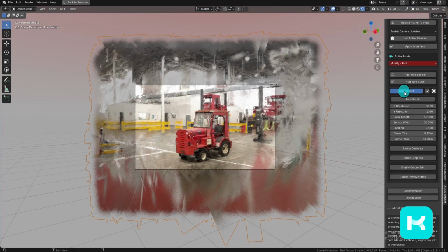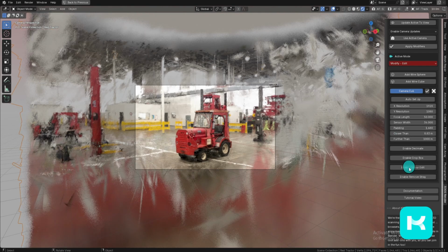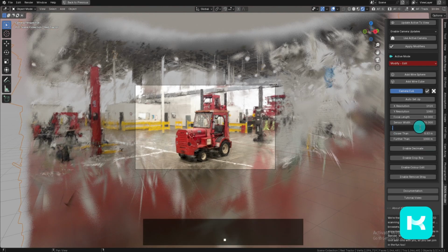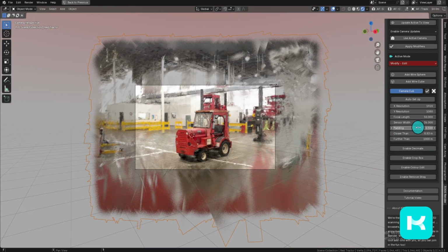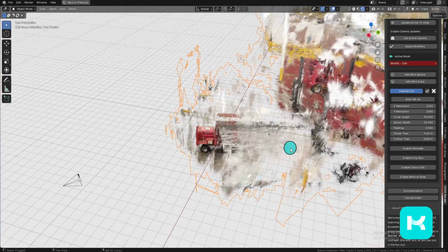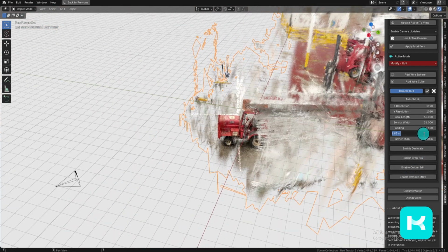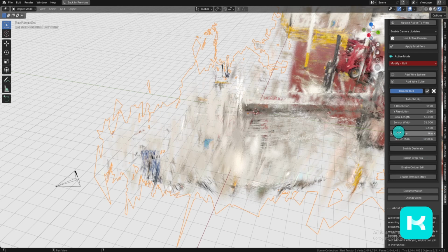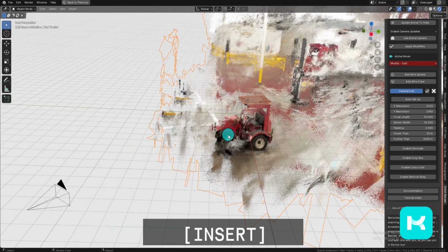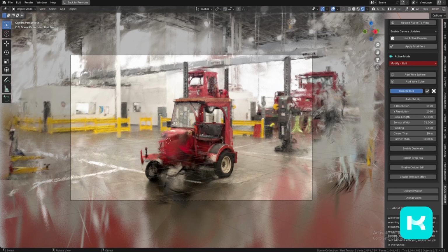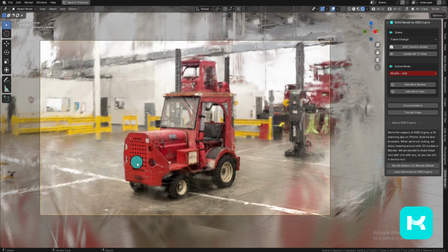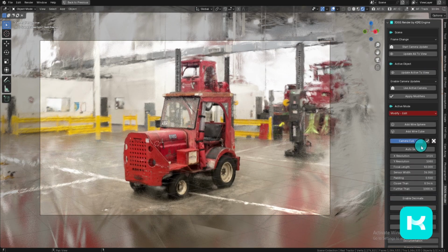Camera culling is the most important modifier in terms of performance and usability. The modifier will remove faces outside of the camera bounds and by distance to the camera. An active camera is required to use the modifier. If the modifier is enabled and no active camera is present, a warning will show. The modifier's settings must match the active camera and scene settings. You can set this up quickly by hitting the Auto Setup button.